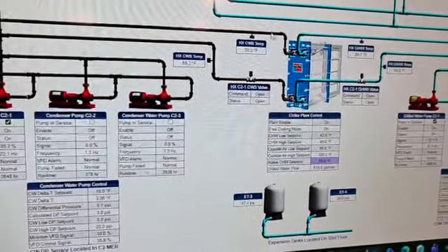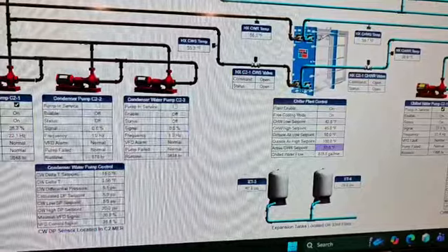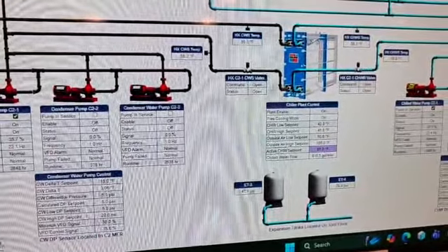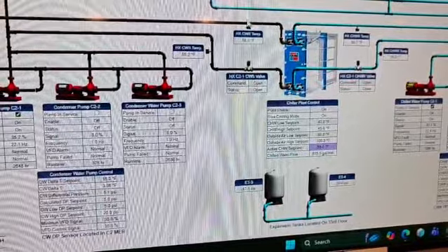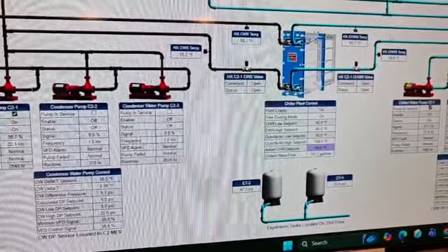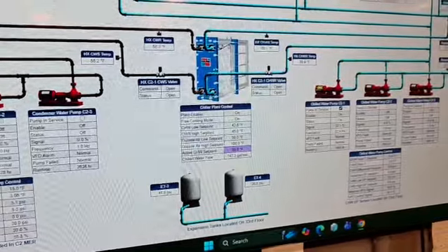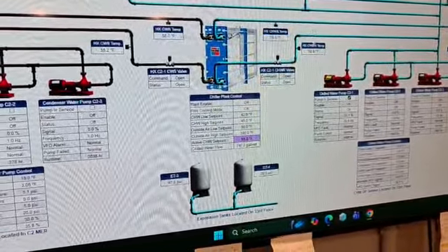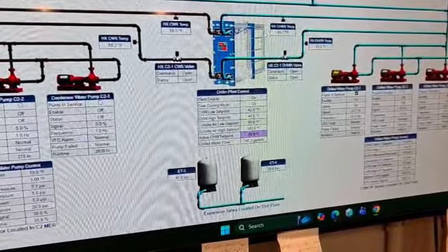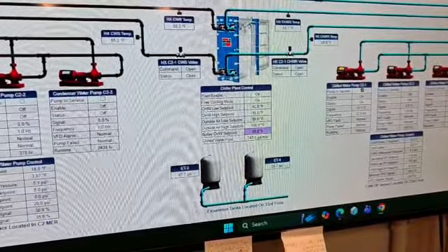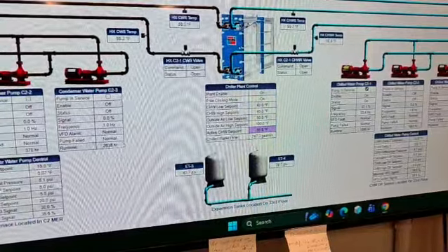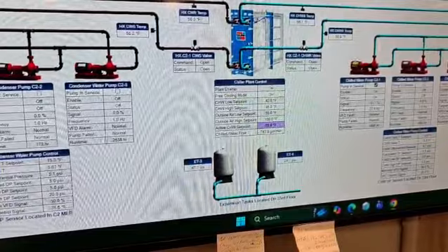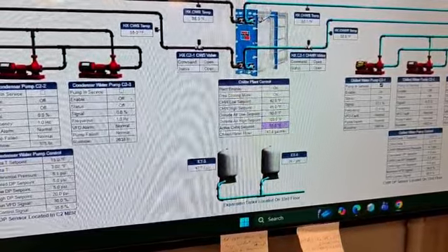And it's the same logic, right? The water from the cooling tower will get into it, actually coming from the bottom. It comes from the bottom, goes inside, and goes back to the cooling tower. And this is the water that you're running through the building. There's almost no exchange. You see 57, 58, because the cooling tower water is good enough. So this is only in between seasons. You're not going to see this running or open. You see the valves are open during summer because you need the water to be even colder.